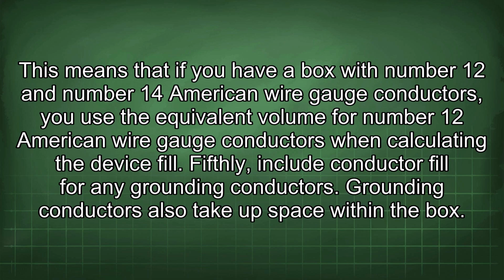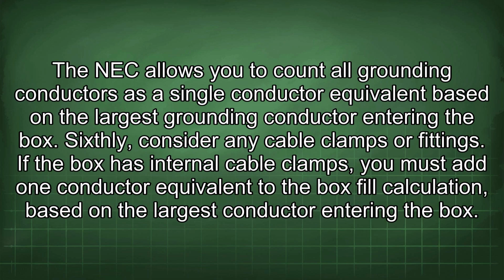Fifthly, include conductor fill for any grounding conductors. Grounding conductors also take up space within the box. The NEC allows you to count all grounding conductors as a single conductor equivalent based on the largest grounding conductor entering the box. Sixthly, consider any cable clamps or fittings. If the box has internal cable clamps, you must add one conductor equivalent to the box fill calculation based on the largest conductor entering the box.